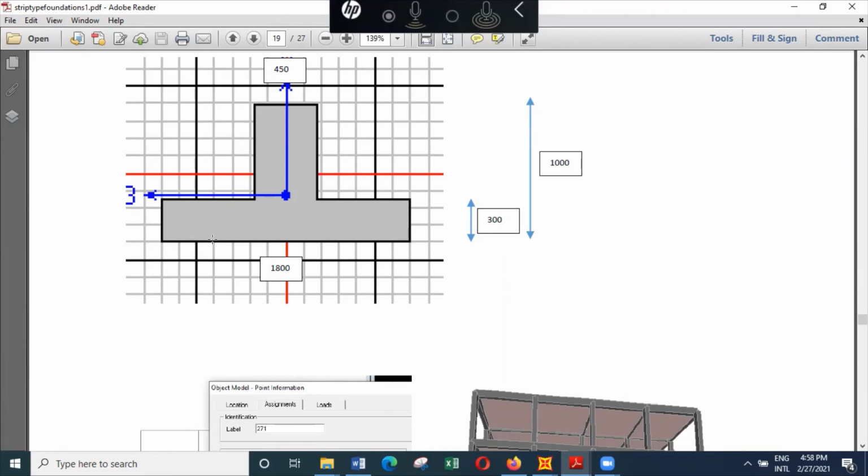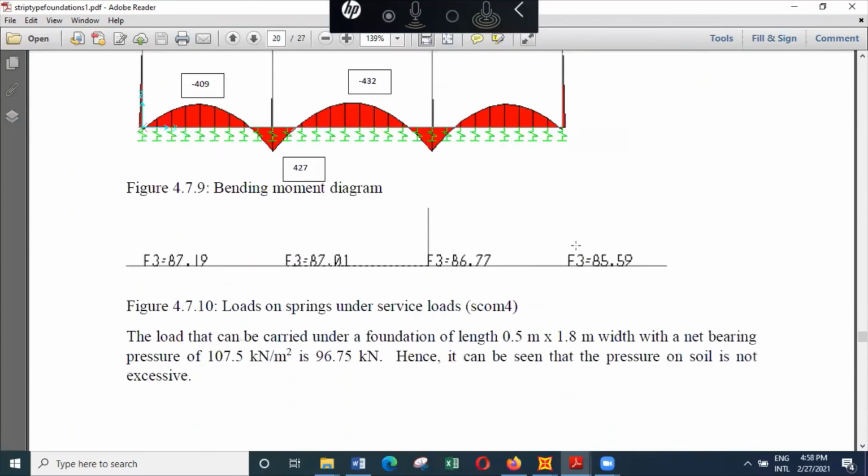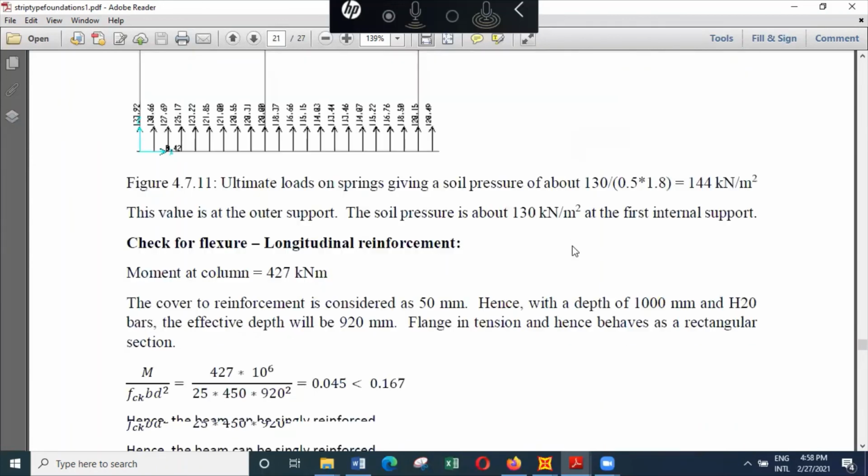And if you divide that 59 by 252 by 1000, because the shear force is over 1 meter length, you'll find the shear force here is only 0.23. And we know always concrete will have a shear carrying capacity in the range of 0.35 and above. So which means the direct shear failure cannot happen here. But I have modified the note last week.